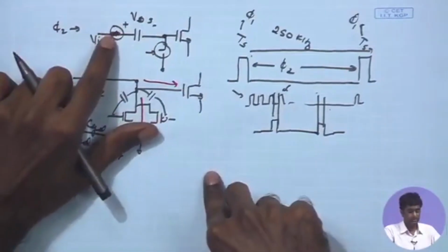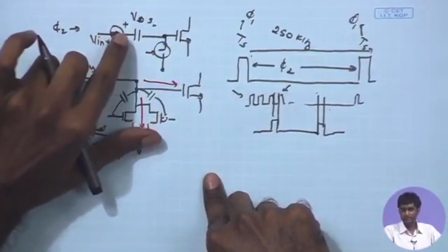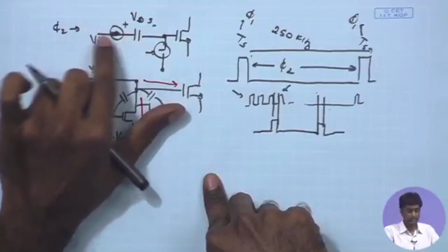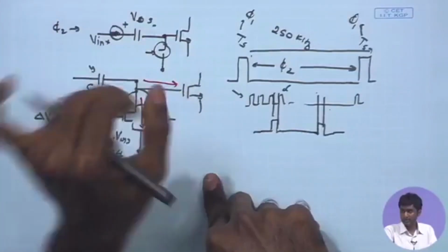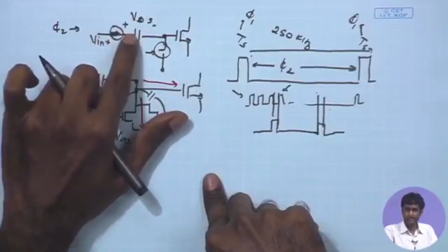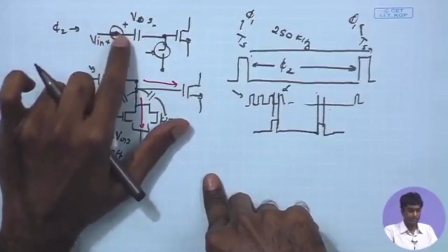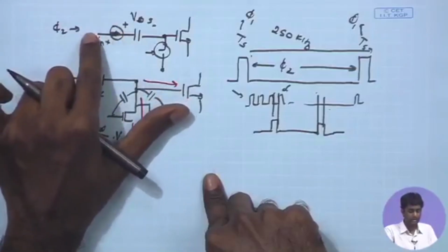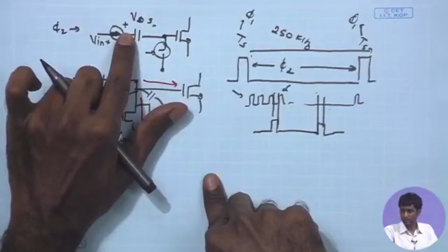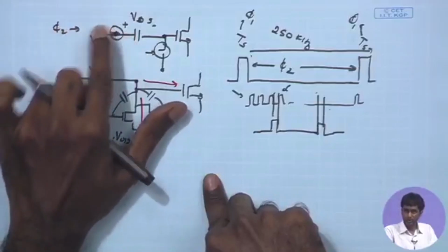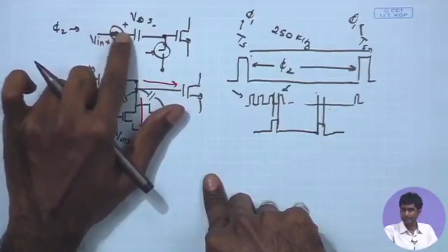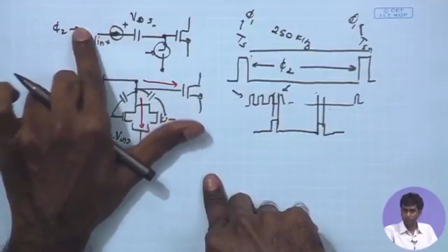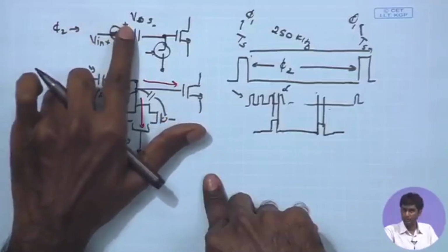As I said, the other switch over here, when it gets open for sampling the input voltage, it will be absorbing charge, and as a result, of course, it will extract some charge from this point. But under that condition it is ultimately going to deploy the V in. The V in is going to be connected to this particular node, and therefore, during the turning on phase, even though it is extracting some charge to form its channel, both NMOS and PMOS of this gate, you have a source over here which is supplying V in. So, ultimately this node will be charging to V in.